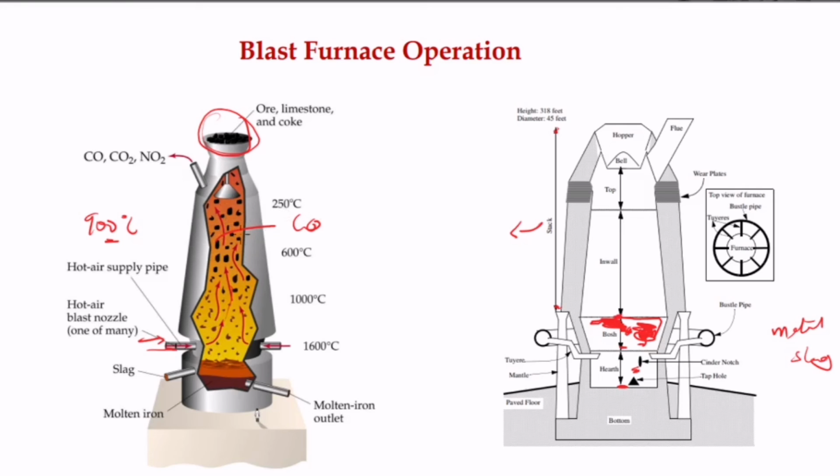And then when the metallic iron is coming down, you have heat generated at the base of the blast furnace. Due to the heat, it melts the metallic iron. Fluxes are also added, right, which react with the impurities so that they will float on the surface of the molten metal, and then it's segregated separately. The molten metal, which in this case is pig iron, is sent forward to the steelmaking process.